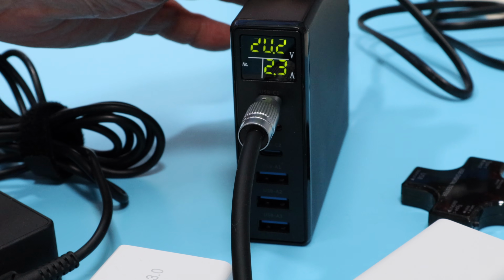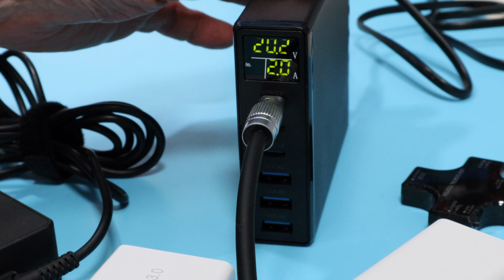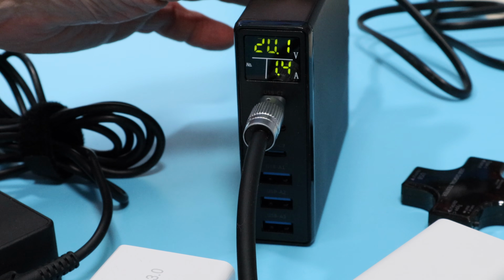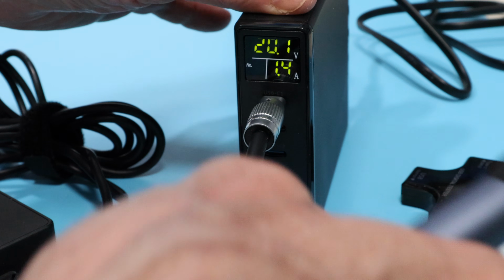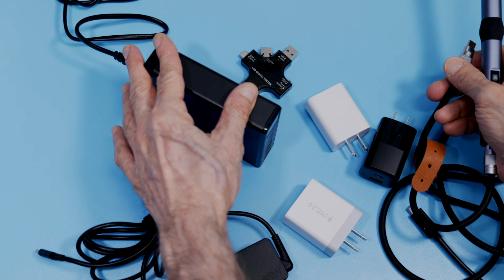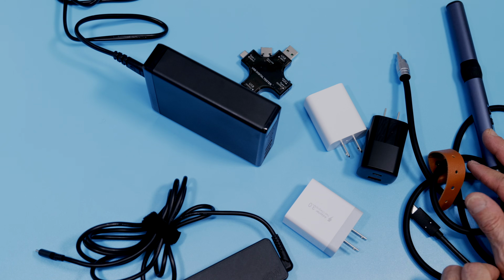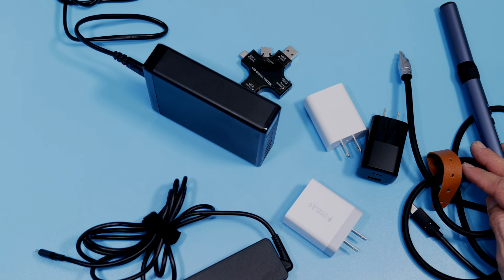And as you can see, the voltage goes up to 20 volts right now, and it's pulling about 2 amperes. Now it's dropping as the iron is heating up, and I'll unplug it at the moment. Now, if you have a USB PD supply and you don't have a display, it's a handy thing to have,